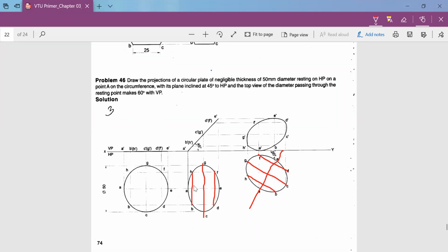On the 60 degree line you will fix the point A. After you get A, you will measure from A to E using a compass, and you make a reference. So you got A and E. After that, you identify from A to this point what the distance is and make a reference point. And again from E to this point, make a reference point. And again from E to the center, make a reference point. You got all the three reference points. Once you have them, just draw perpendicular lines to our 60 degree line. It should be exactly perpendicular. I have shown you only roughly.